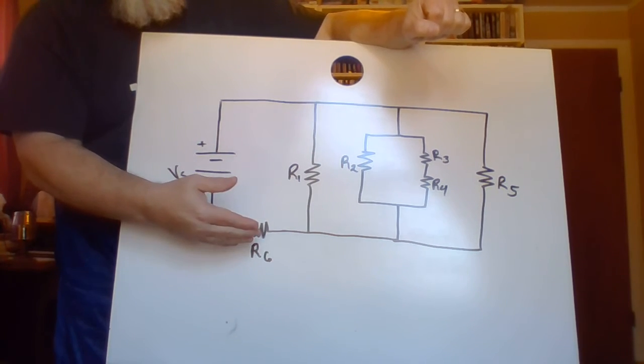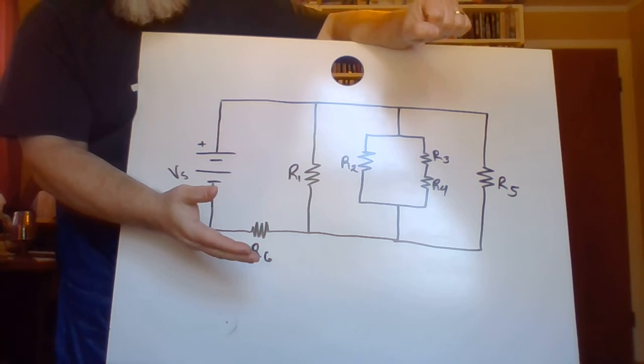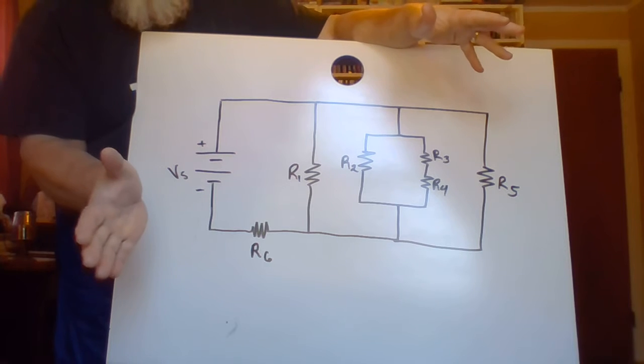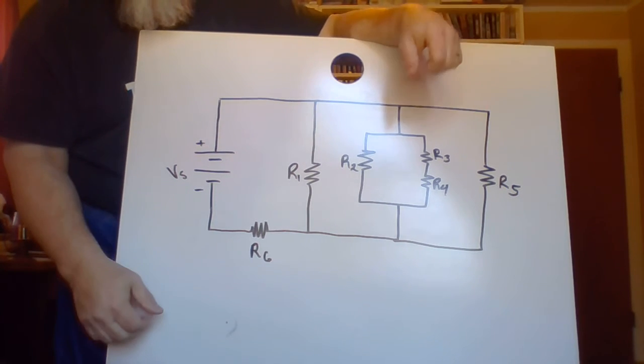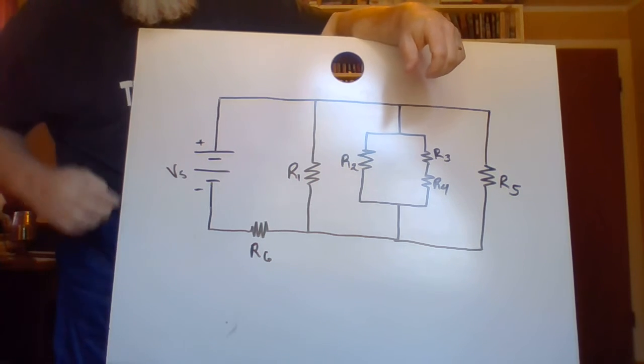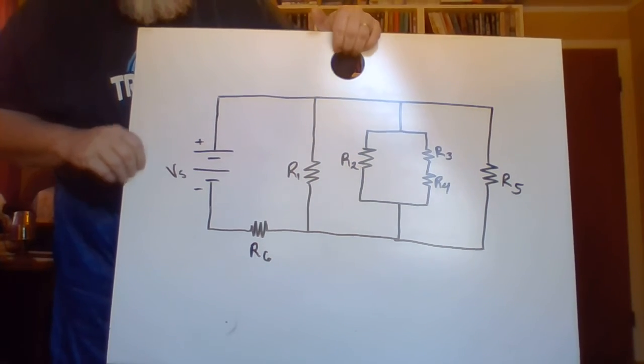A switch essentially goes from low resistance, it's a wire, to ultra high resistance because now it creates a gap. It's air that's in there, so the conduction goes away. That's why switches have to be in series with what they're controlling. Okay?